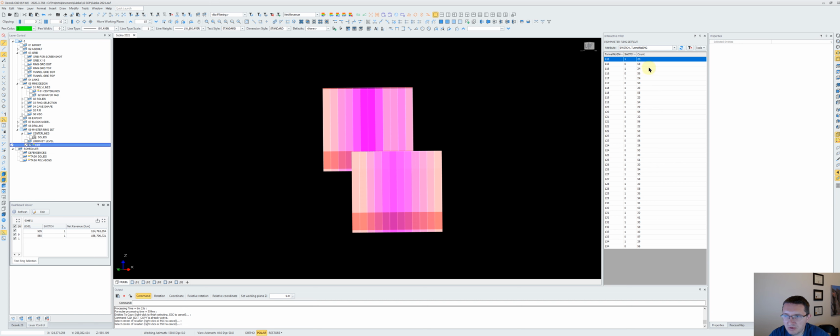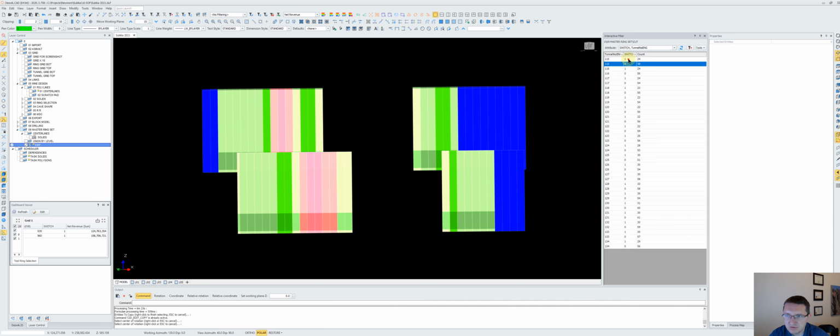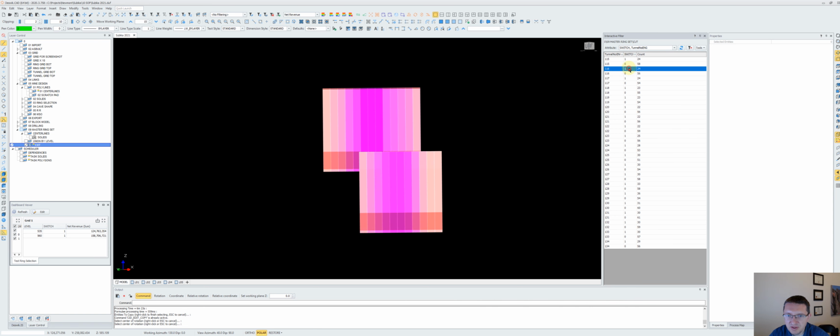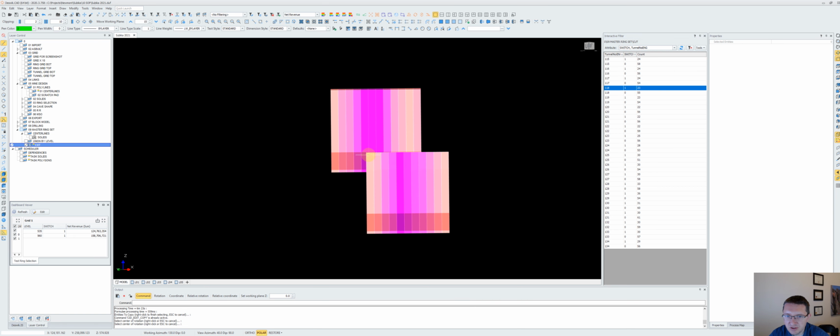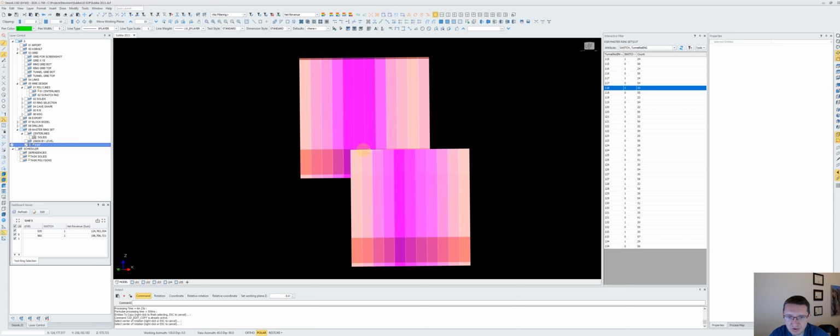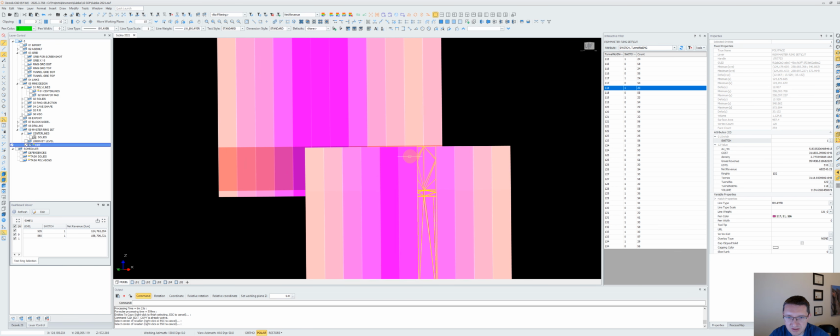We have tunnel number 115. These are the ones that are on. These are the ones that are off. And so you can step through these and make sure there's the two things you want to look for is overlap. You want to make sure there's enough overlap. There will be a geotechnical constraint that says you need at least 4 of these, or at least 2, or at least 10 overlap right here. You want plenty of overlap. The more overlap you have, the better.